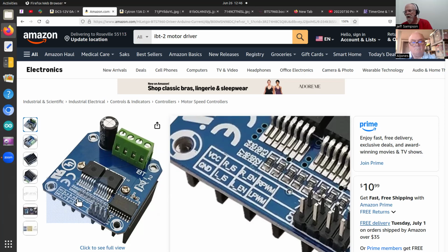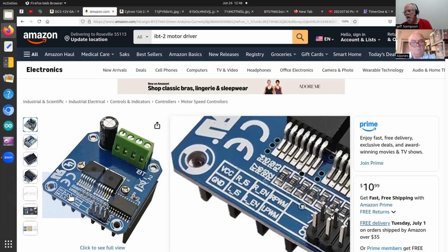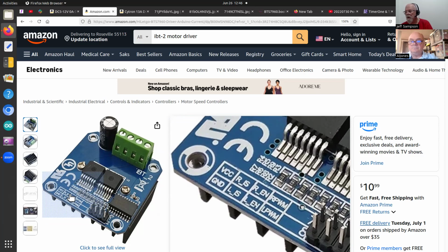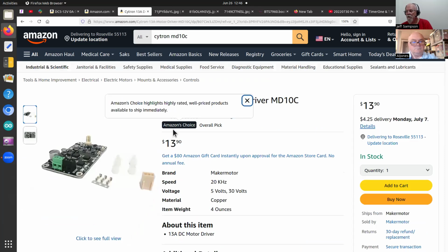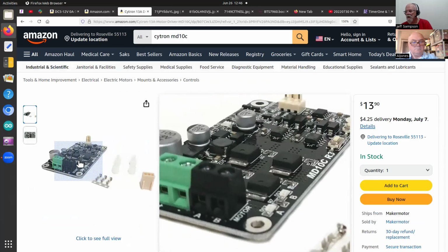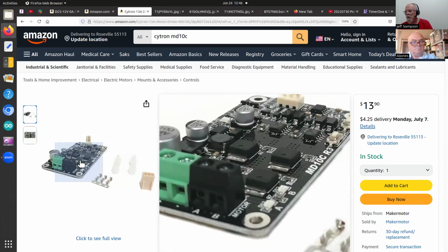And these other signals there, that RIS and LIS, those are actually outputs that we were discussing before the meeting. It says those might be current sense outputs, but you can also get some kind of, if you get an error, somehow they switch that to diagnostic, and I'd have to read through that to figure out how all that stuff works. And then another option is I have, for instance, here's a Cytron single channel 10 amp.